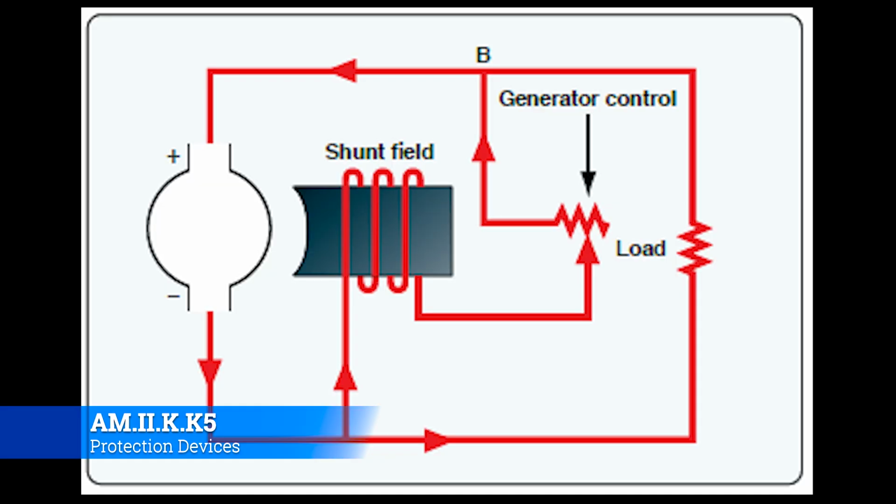Okay, so a voltage regulator does exactly that. It just regulates voltage. Now, aircraft are meant to run on very specific voltages. Most of them are like 24 volts or 28 volts, so on and so forth, depending on the type of aircraft that we're dealing with. Is it a heavy commercial airplane? It's going to have a 28 volt DC system. If it's smaller ones, maybe it's 24, maybe it's even 12.